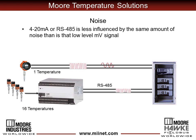Or a better solution might be to convert those low-level millivolt signals to high-level signals, and do so as close to the sensor as possible. The same amount of noise will affect high-level signals less than low-level signals. Signals like 4 to 20 milliamps, HART, RS-485 survive most typical levels of noise.